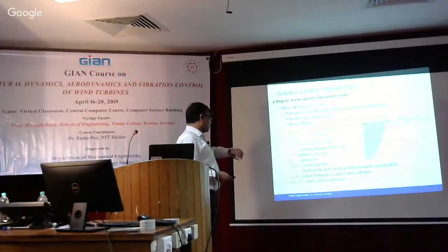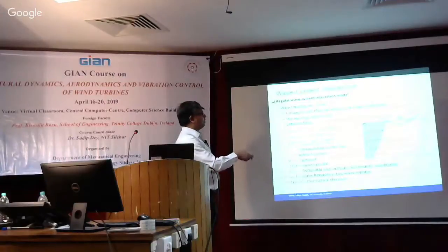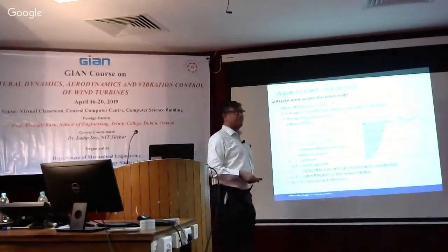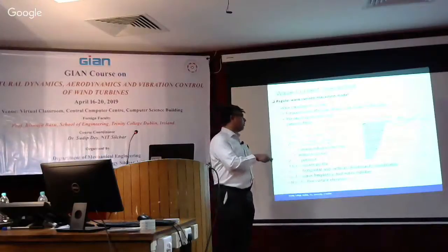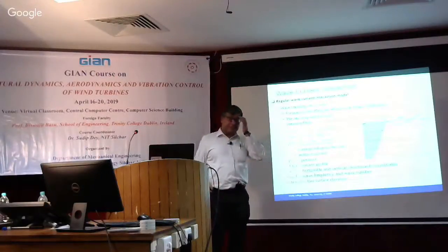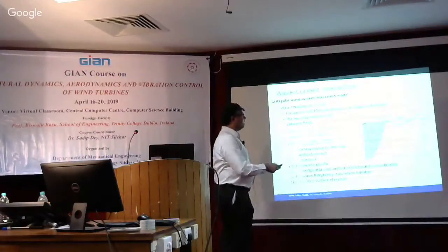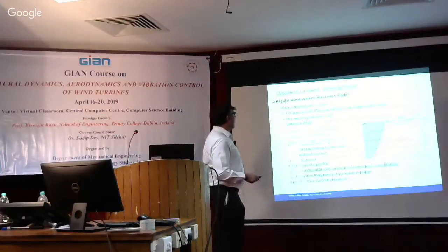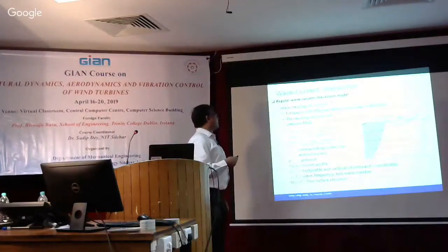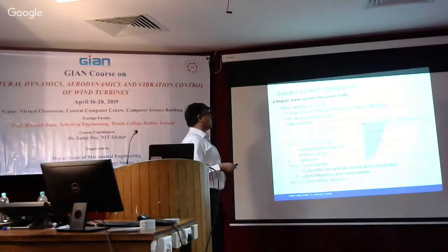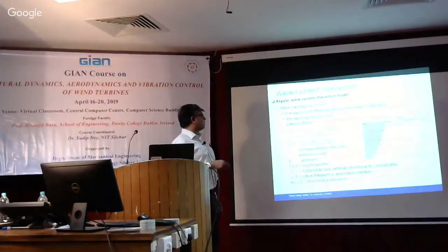Okay, so now we move into the wave current interaction model. And here, as I showed, this is the wave traveling on this shear flow. So based on your basic fluid mechanics, you know that this is a laminar shear flow, and this is the wave which is generated at the top. Normally for laminar flow, you don't see this happen. But we have a wave here, and this is now interacting with this current. And obviously, because of the nonlinear dispersion and the wave traveling on current, there is a frequency shift, a Doppler effect that modifies the spectrum. So because of this, there is a shift in the frequency.